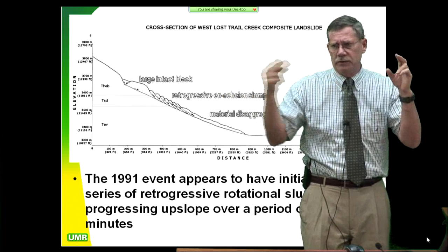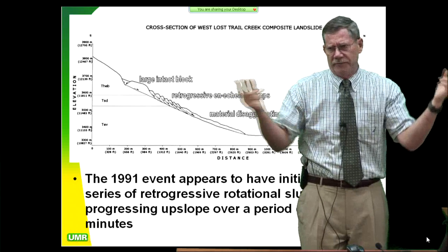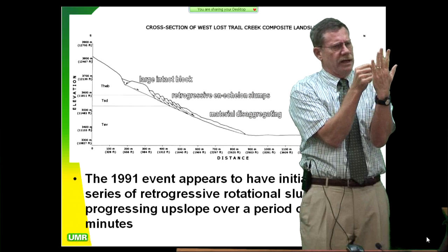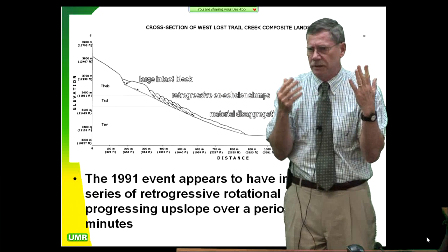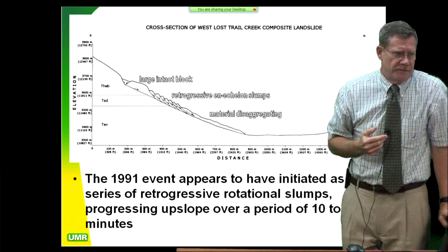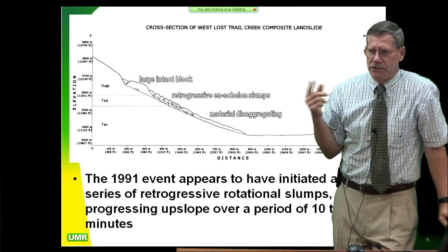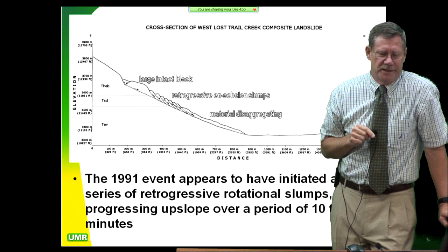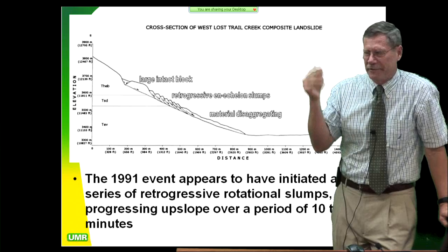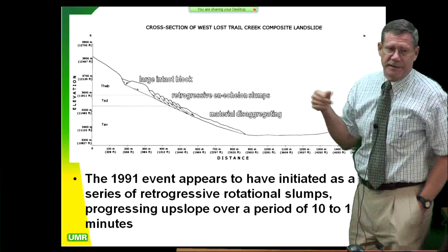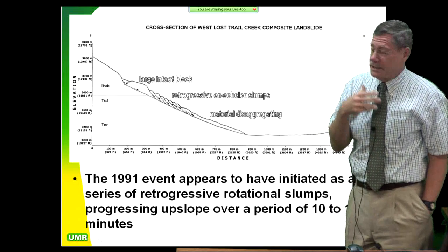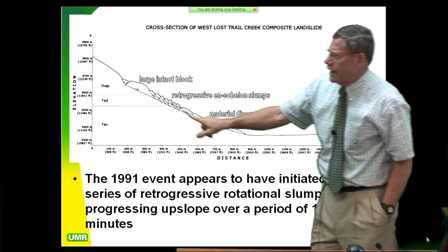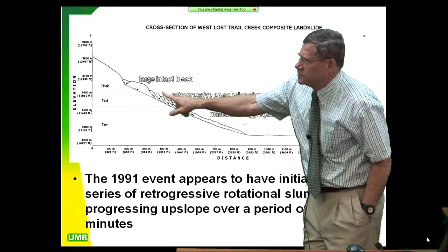Now I can take the 2 new photographs and the old photograph, digitize all of them, and I can look at it in stereo, and I can make very precise measurements on those terrestrial photographs. That is an old German intelligence officer trick that was used by their naval attachés in China and Japan and other places. So I've used that particular methodology many, many times on doing forensic assessments. And by doing that, I can make very nice measurements.